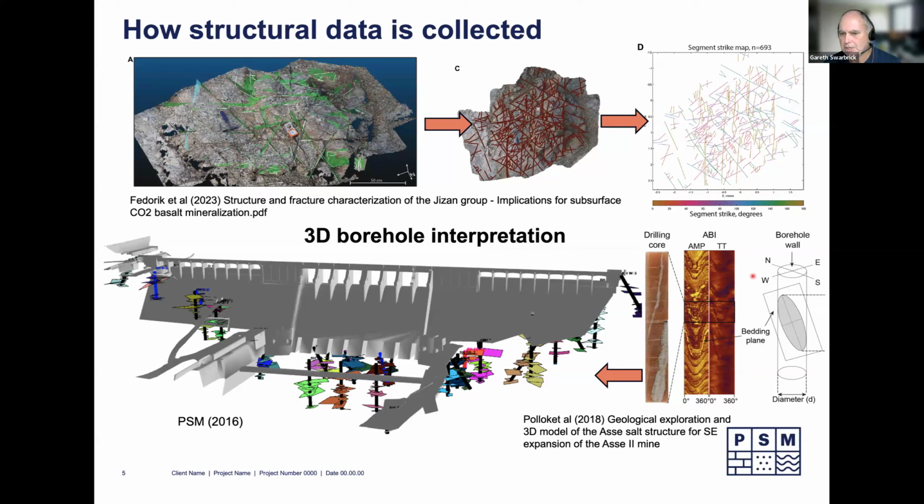Another way we do it is downhole tomography using acoustic televiewer and optical televiewer techniques. Those techniques allow us to pick up the structure within a rock sample and then interpret that structure, its orientation, the defect, and the inclination of that defect, as well as the type of defect. That's also very important. This is a real case on a dam we worked on a few years ago, where we can create from boreholes representations of different defects, and the different colors represent their type or what rock unit they lie in. So we have quite a nice distribution in 3 dimensions. We are trying to understand, in this case, how those features might connect and how they might interact with the dam structure once it's loaded by water, by earthquake, or by other means.